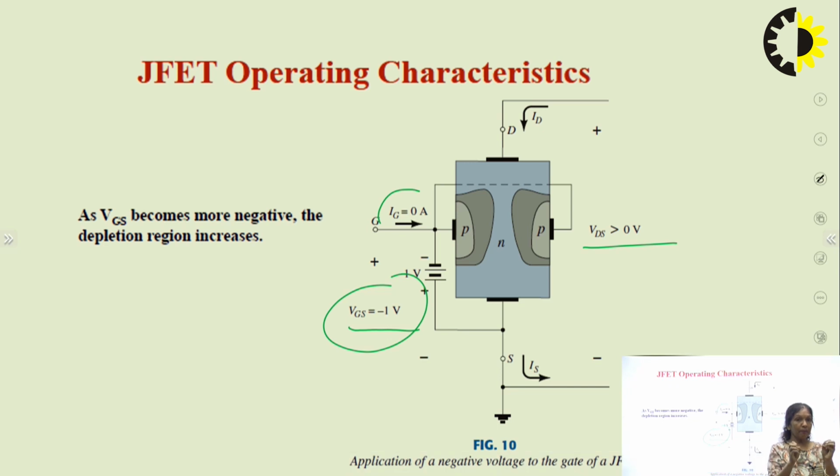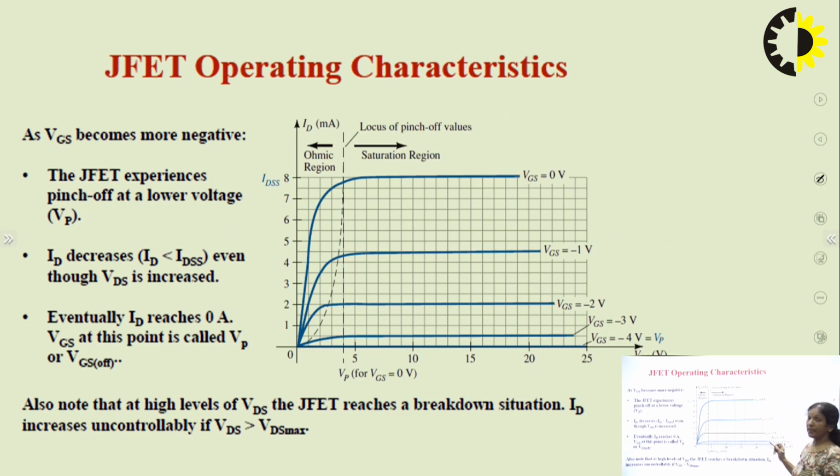And if the depletion region grows at a faster rate, what does it mean? It means that the number of charge carriers which manage to pass through the path between the depletion regions will be less, and if the charge carriers reduce, that means the current reduces. If the current reduces and the path is getting narrower at a faster rate, that means the resistance is also changing.